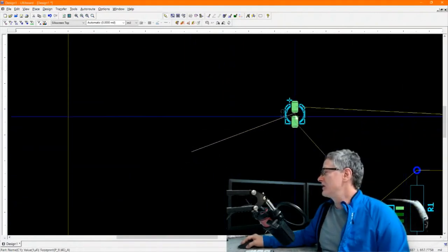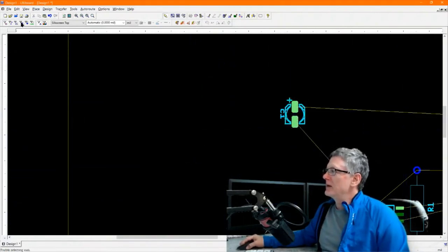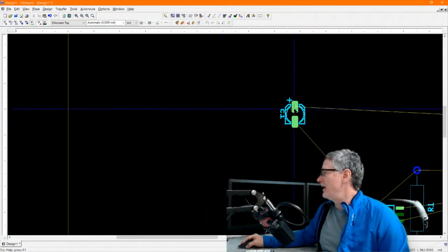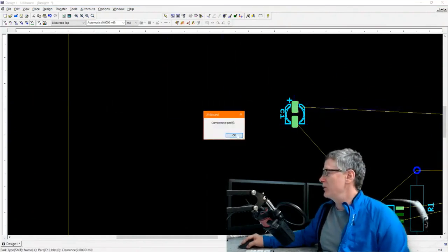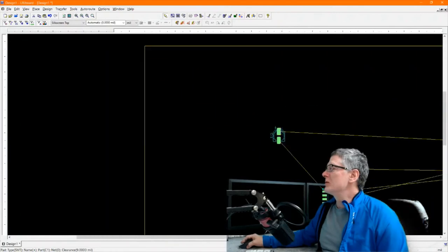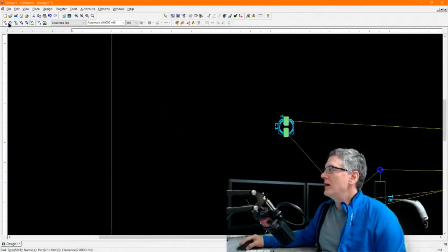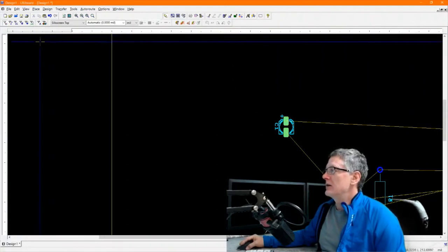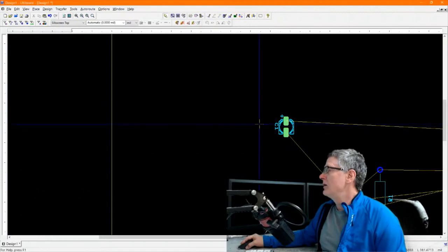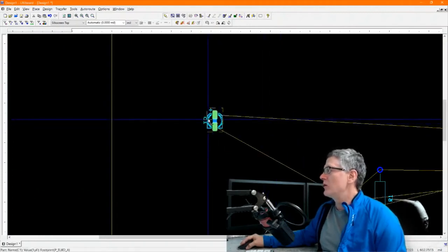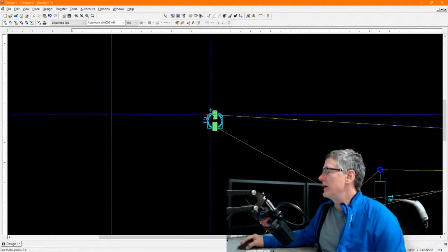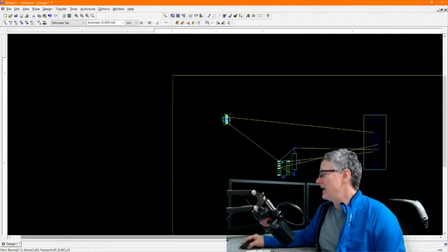And then you get in there and you grab the part, or maybe you accidentally grab the pad. You're trying to grab the pad and it says it can't move pads. So usually when I'm doing placement, which is figuring out where your parts go, I will basically have it so I can only choose chips, and I will deselect everything else so that I can't accidentally grab it. So now I can grab only the whole part. I can't grab the name. I can't grab a pad. So that's usually handy to start with.